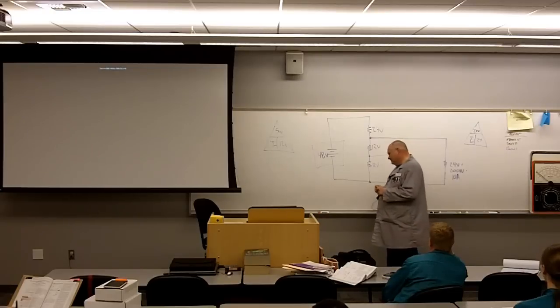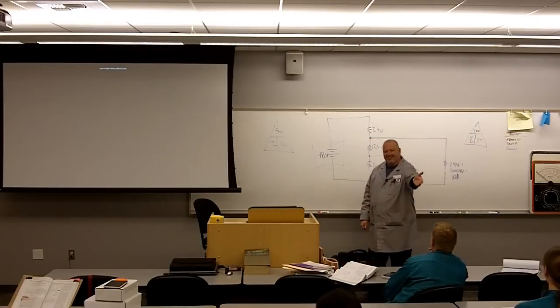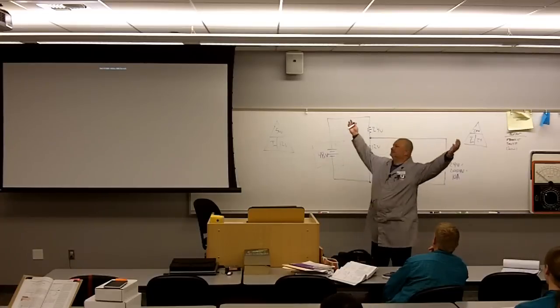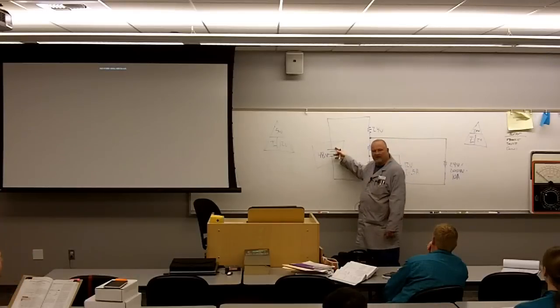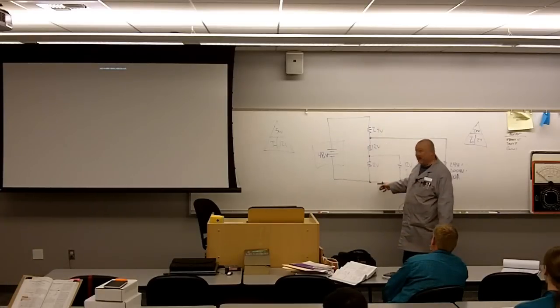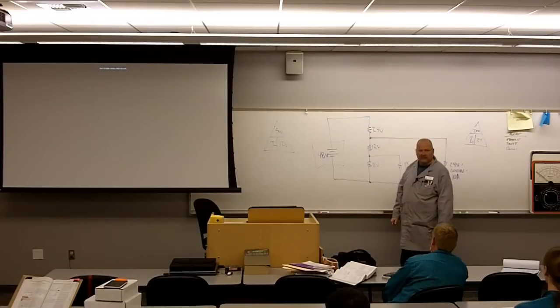Come on, guys. Quote me what I've been quoting you. Your drop has to equal the rise. Absolutely, because the drops have to equal the rise. I'm putting 48 volt rise in. I'm getting 48 volts of drop. 12 here, 12 here, 24 here. All voltage drops present and accounted for. Make sense? Okay, so this is cool.